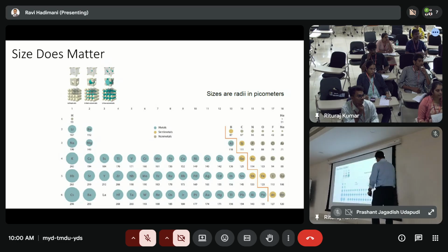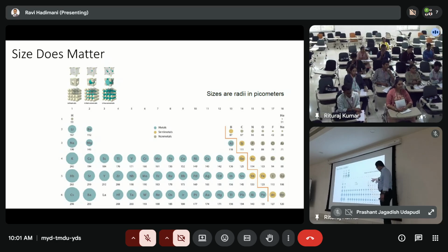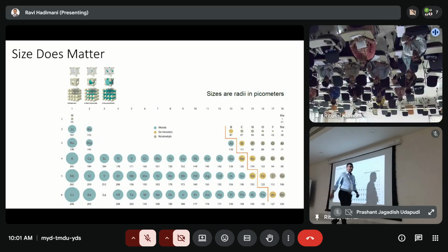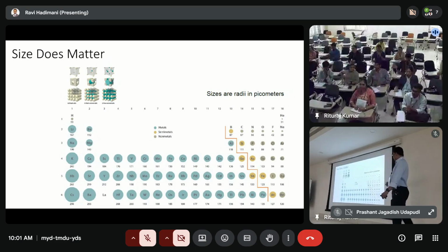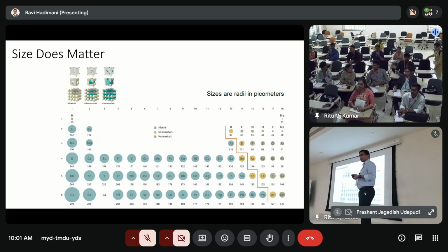Okay, silicon is the most preferred, but if you are using a silicon wafer, that means you are restricting yourself to only some of these atoms here. So you have to move away from silicon wafer if you have to use hafnium, tantalum, or tungsten, platinum, gold. So you have to match the atomic radii between the substrate and your deposit.